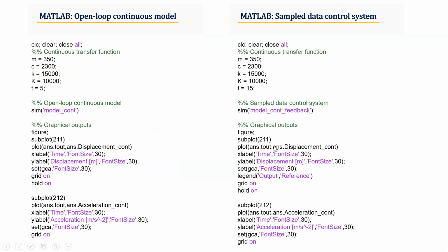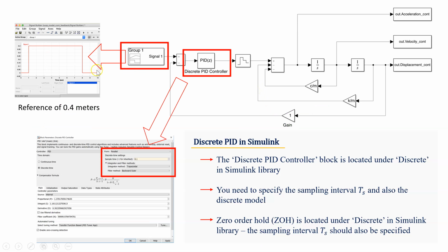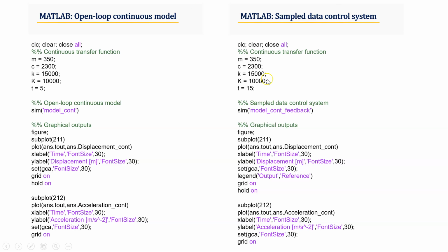So, let's go back to the previous slide, this is the code that I've used to simulate this. If you look at the signal builder, the time period that the step input is applied is effectively 7 seconds with an offset of 1 second. I put the offset on just because it's good for visualizing the graphical output, comparing the input with the output. I've run it for 15 seconds, so we can allow the system to return back to displacement equals 0.